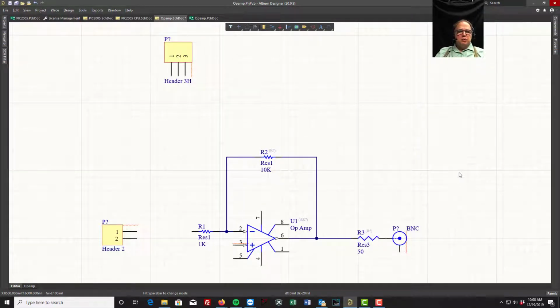This is a visual representation of what's going to go on the board, and it's our classic engineering notation. If I show you this symbol, you know it's a resistor. If I show you this symbol, you know it's an op amp. One thing we don't want to see in these courses is somebody putting this symbol down and saying, oh, well, it had the right footprint, and so I just put this down, but it's really a diode. Or they put this one down. Oh, yeah, I put that down. I'm using a photo sensor. I just put this down because it had the right footprint.